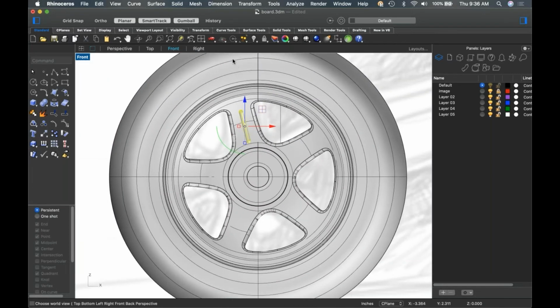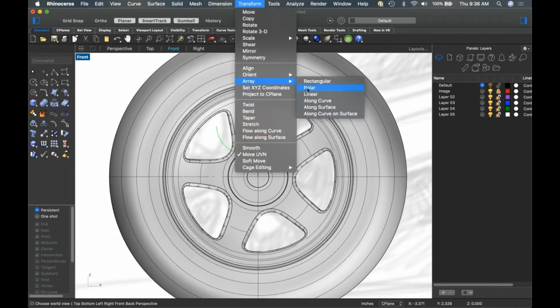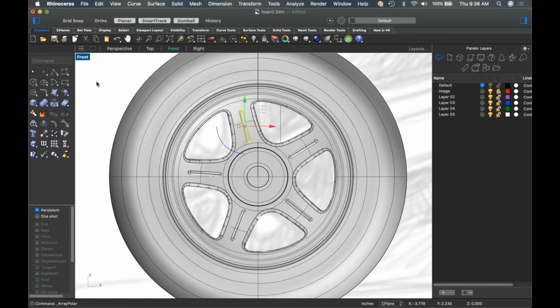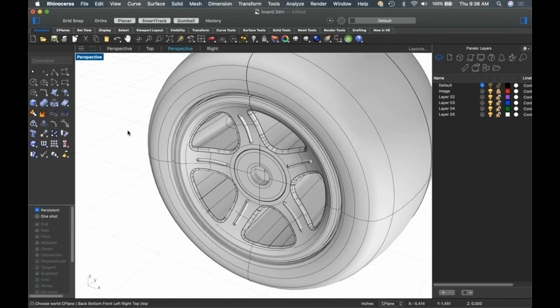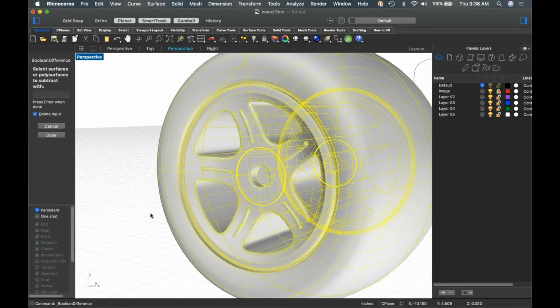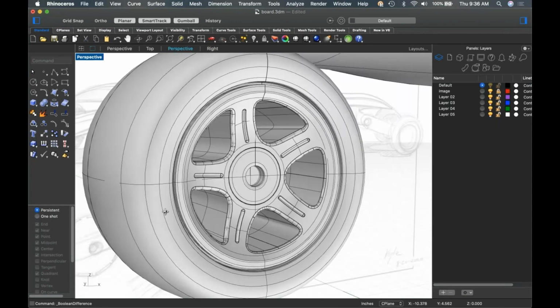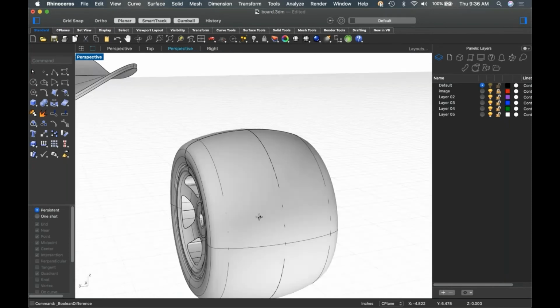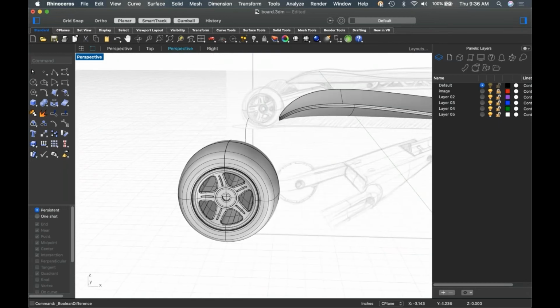And it's recessed in the drawing, so let's go ahead and do that. And we can just use the same settings we did last time. Do a Boolean difference. And there's our little recesses. And we could add a little blend on that, but I'm not going to do that for this because I think we've got the idea now.